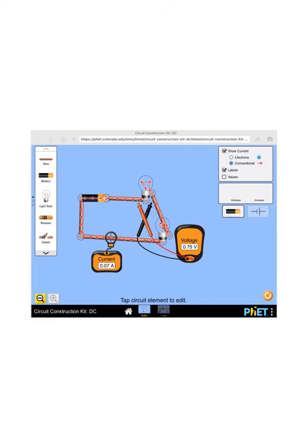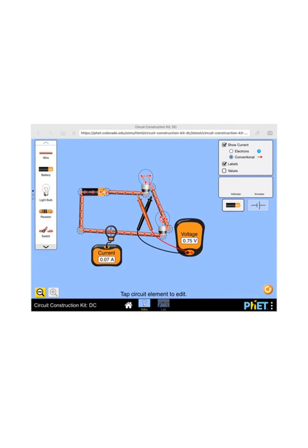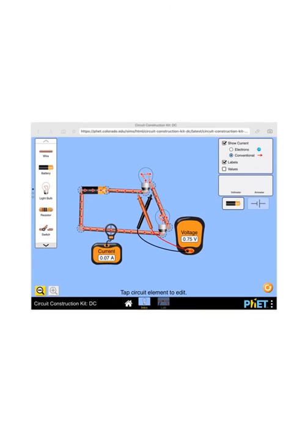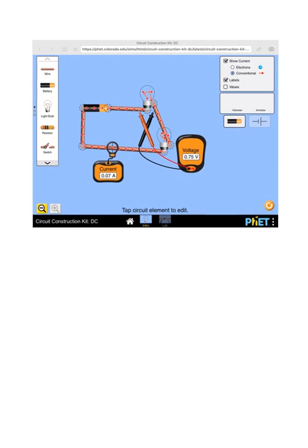If we place a second light bulb in series in this circuit, then what we see is that the current drops even more because we've placed more resistance in this circuit, but so too has the voltage changed across light bulbs. We see that the voltage is 0.75 across each light bulb, rather than the 1.5 it were before. It's almost like our voltage got cut in half. So, why is that? In order to understand this, we need to talk about one final key term, and that is electrical power.